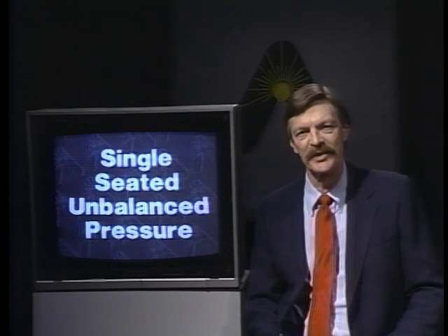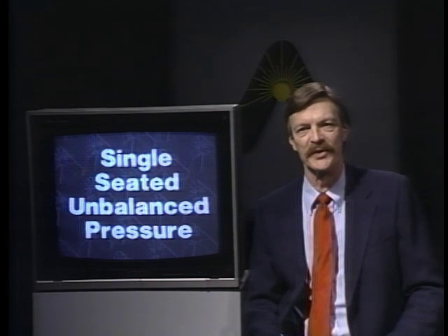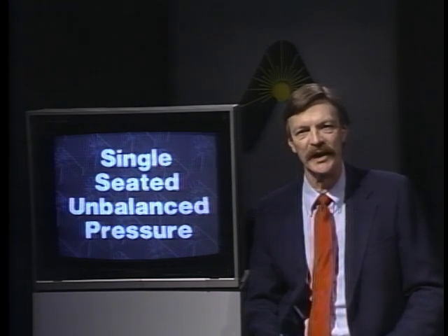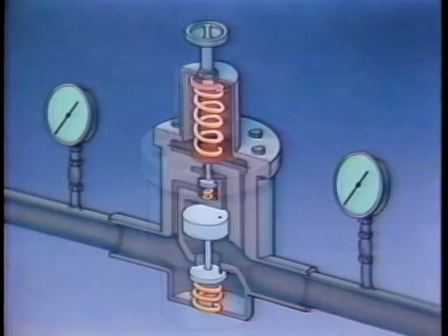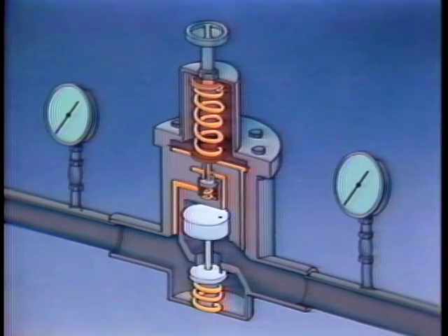The only possibility we've discussed so far that is suitable for steam service applications is the single-seated, unbalanced pressure valve, with all its inherent inaccuracies. However, as I mentioned before, there is a second design style for PRVs. This is a pilot-controlled pressure-reducing valve. The notable difference is all the internal channeling and this second independent valve.